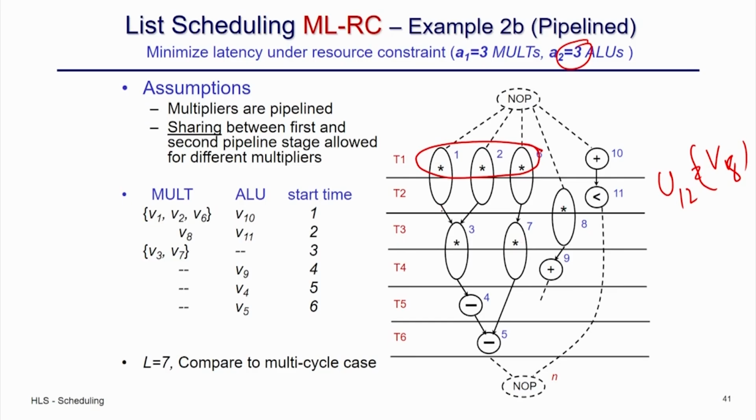So, in time step 2 all 3 are finished, and this is continuing. And there are 2 operations now available. So, I can actually schedule all of them because I have 3 multipliers. So, I can just start all these 3 in time step 2 and so on. So, if I do this in a pipelined manner, I will take 6 time steps to execute this, where I have 3 multipliers available and all multipliers are 2-stage pipelined. Okay. So, with this I finish the discussion on scheduling.